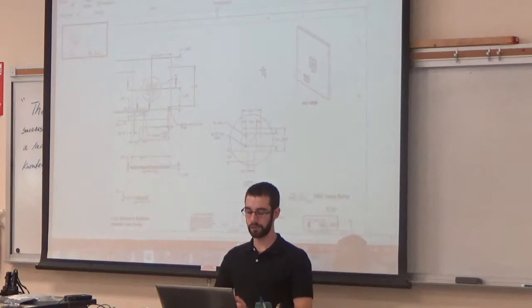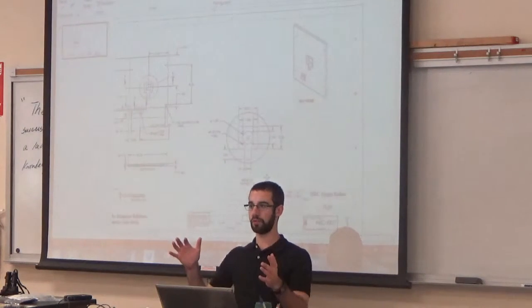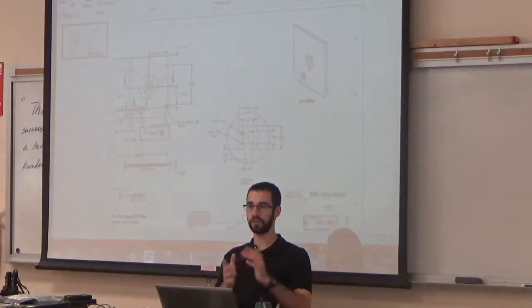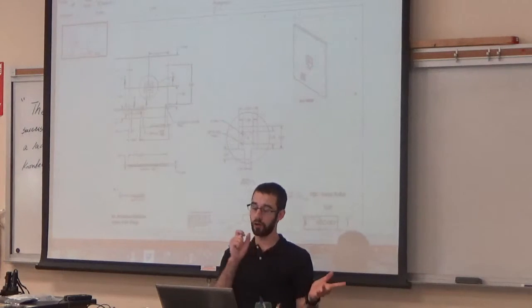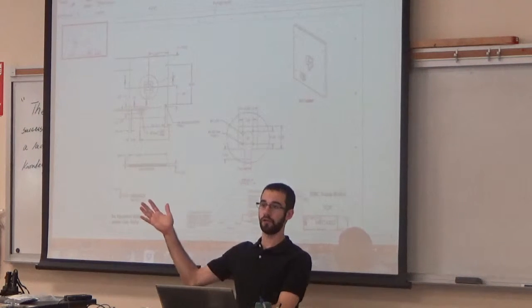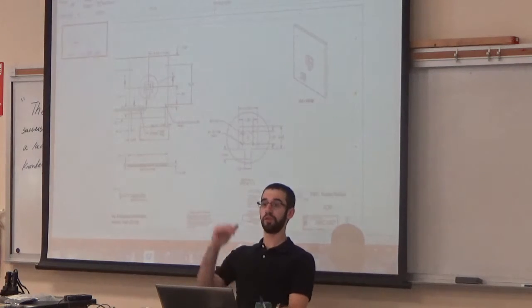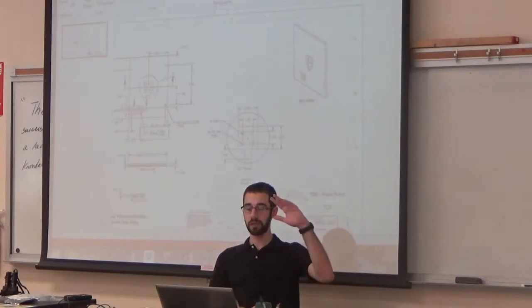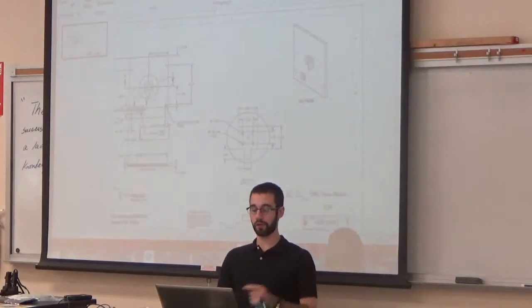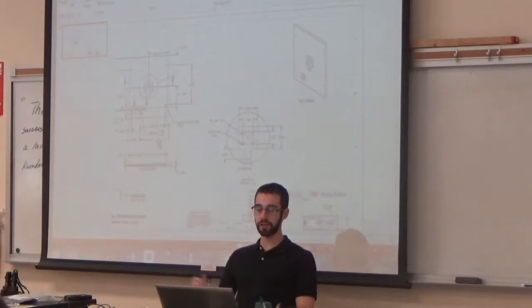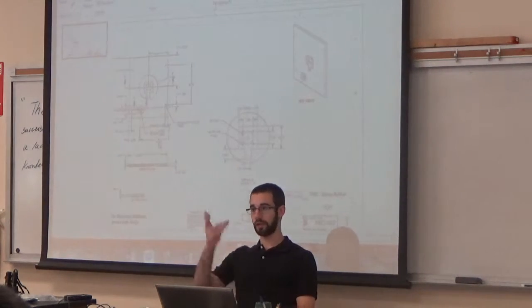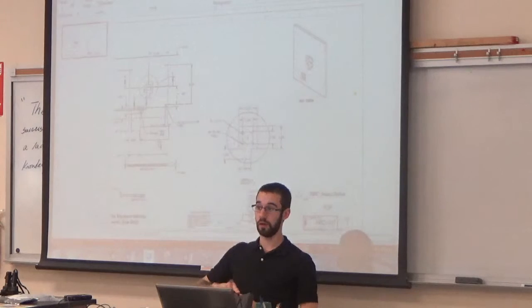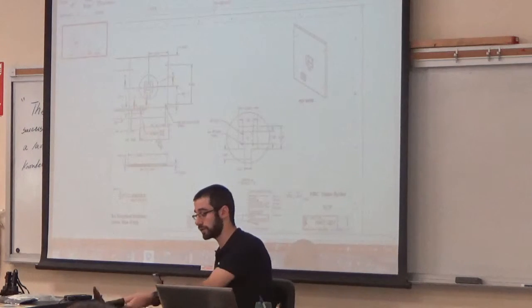For all drawings, you're going to have a designated typical tolerance. You call it out in your notes. But if you have something that needs a different tolerance, you call it out there. So it can be plus or minus 5 thousandths of an inch, just plus 5 thousandths minus 0, plus 5 thousandths minus 10 thousandths, something like that. And that's basically the range for that part. So for this dimension, it can go from 0.871 to 0.866 in terms of what I can measure. And that's basically just taking a set of calipers, or better measurement tools, and measuring, like this.